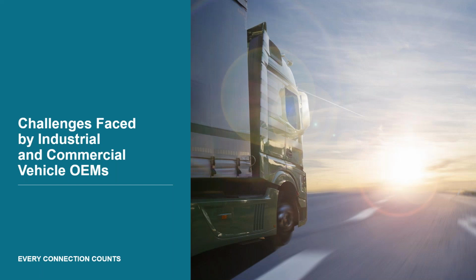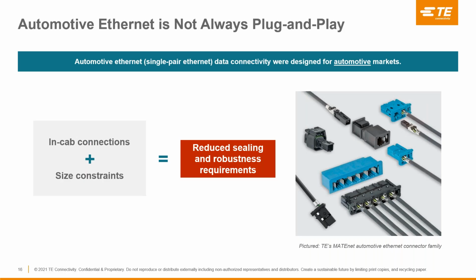So what are the challenges faced specifically by industrial and commercial transportation OEMs? As we look at the automotive Ethernet connectors that are available today, and you'll see here pictured to the right, this is the TE Connectivity MATENET product line, prolific in the automotive industry, and you'll see it's very, very small, small latches, multiple ports for multiple connections within a vehicle. And here in the automotive industry, the goal was not just the higher speed capability, but was also very compact size, very tight spacing to take up as little real estate inside the vehicle as possible. And in most cases, these are unsealed connections, as in most of the data connectivity hubs and communications are tucked nicely inside the warm and air-conditioned interior of the automobile itself.